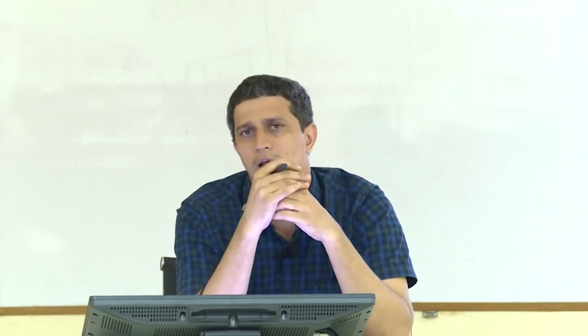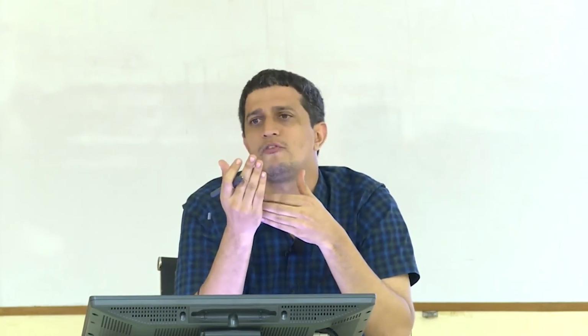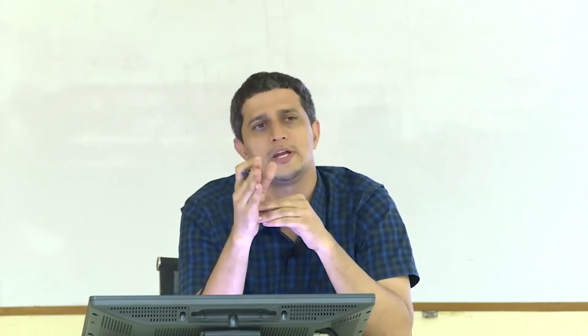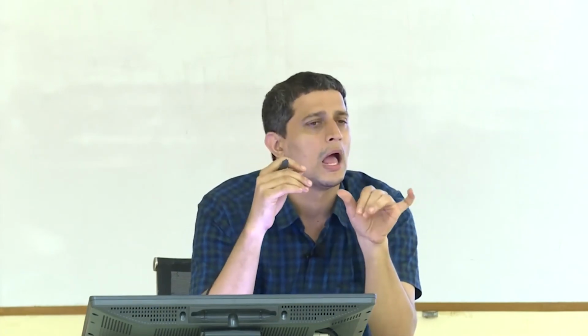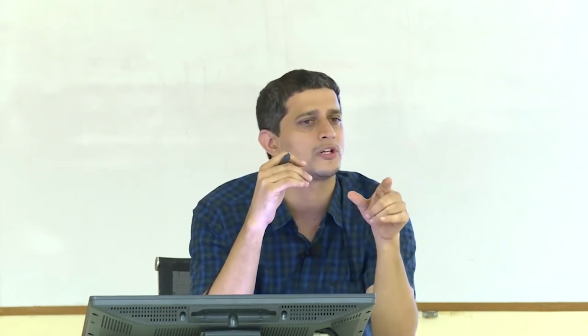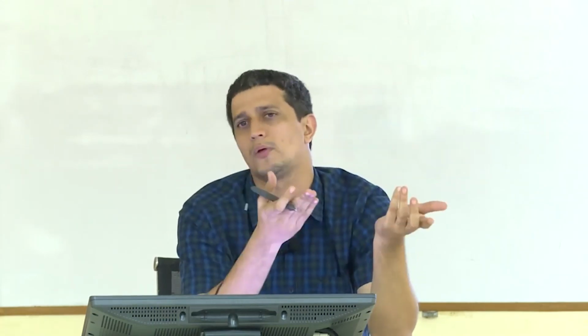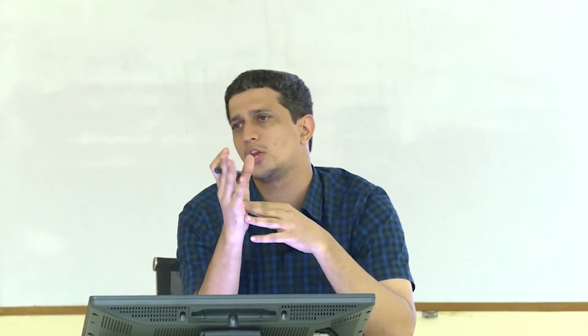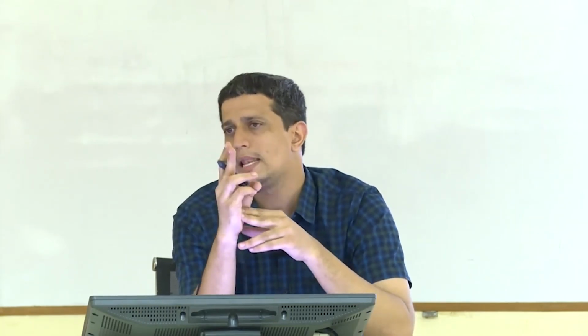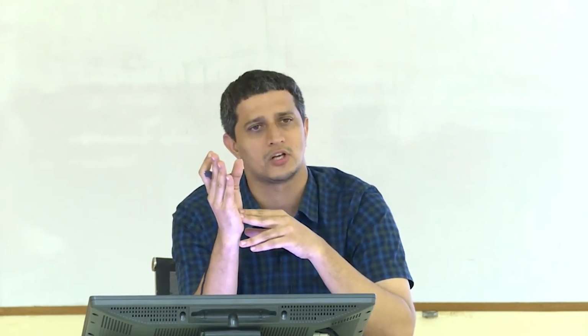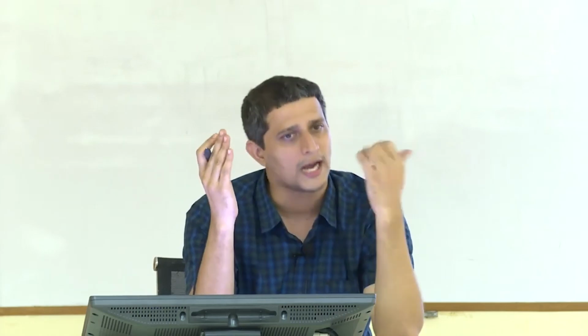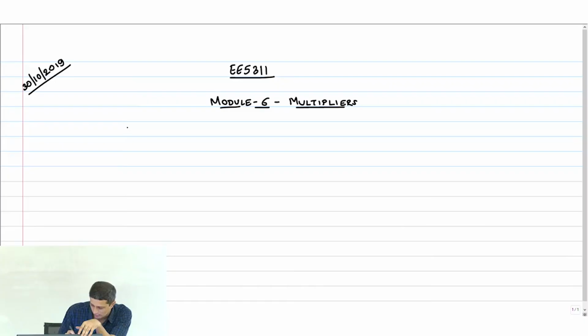Obviously, the way you do signed multiplication and unsigned multiplication are very different, which means that if I give you an n-bit number, unless I tell you whether it is a signed or an unsigned representation, you cannot perform the multiplication. That's why in your microprocessor, you have 2 different instructions called mul and imul in the x86 architecture. One is signed multiplication, the other is unsigned. Today we will see why and how the hardware has to be different. So let's start with an array multiplier.